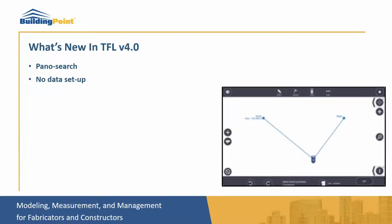They also got the new no data setup command available. Really neat feature when you have existing conditions to survey, but no control points have been made available yet. So you can show up on your job site, open a brand new job with nothing inside. You can either mark your control points that you want to establish, or do not mark them and just go on the fly with your rod. Take 2 shots, respecting the resection criteria, so 90 degrees between your points and your station. And then when you've taken your first 2 shots, hit the setup button, and the instrument will be positioned with regards to the 2 shots you've taken.